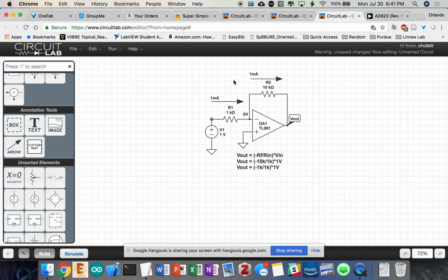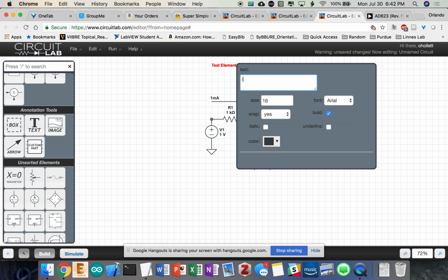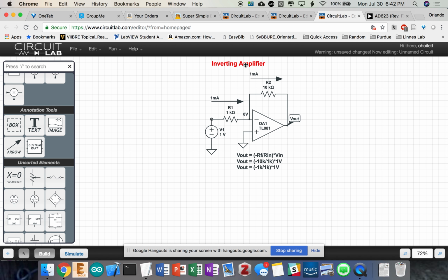Yeah, so this is an inverting amplifier, and that's just a standard equation. Basically, by manipulating the orientation of the resistors, where your source is going into, and the size of the resistors, you can get different gains. There are basically endless configurations of amplifiers you can imagine.